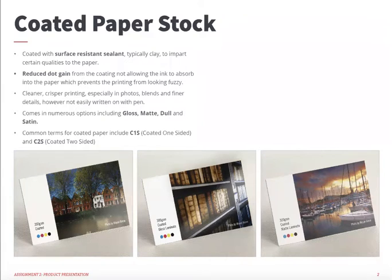However, one of the disadvantages of this is that the paper isn't easily written on. Coated paper comes in a few different options, including gloss, matte, dull, and satin finishes. Gloss coated paper has a high sheen, less bulk and opacity, and is typically less expensive than dull and matte paper of the same thickness. Satin coatings are less shiny than gloss, but the colours are sharp and vivid. Matte coatings are non-glossy with very little sheen. They are more opaque, contain greater bulk, and are higher in cost. And dull coated paper has a smooth surface that is low in gloss and falls between matte and glossy paper depending on the manufacturer.